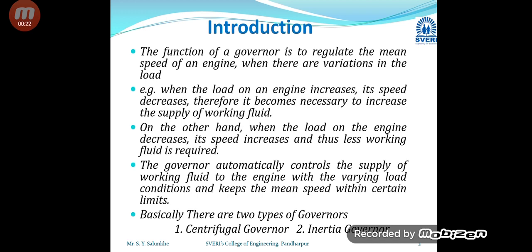Now when speed is varying, because of an increase in load the speed will decrease, and it is necessary to increase the fuel supply to that engine, or it may be considered as working fluid. It may be fuel or it may be steam in the case of steam engines. Nowadays we are not using steam engines, so we can say the fuel supplied to the internal combustion engine has to be increased. On the other hand, when the load on the engine decreases, its speed increases, and thus less working fluid has to be supplied.